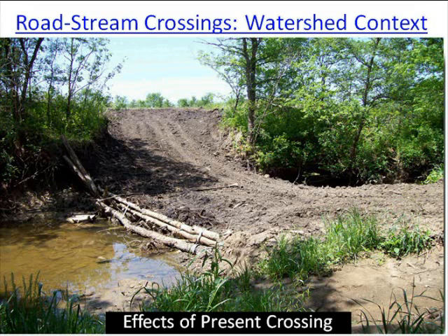So determining the watershed context of a crossing site helps you begin to quantify the potential stream flow, sediment, and debris transport regime that may occur at that site. Site geomorphology helps you understand a number of the design challenges you might meet and also provides insight into the type of structure that may best fit the crossing.